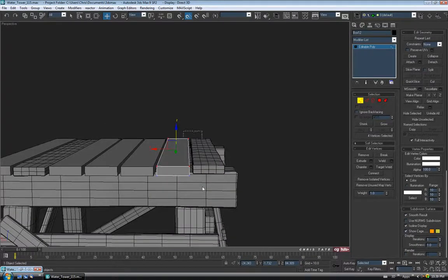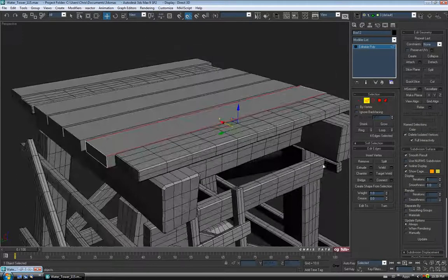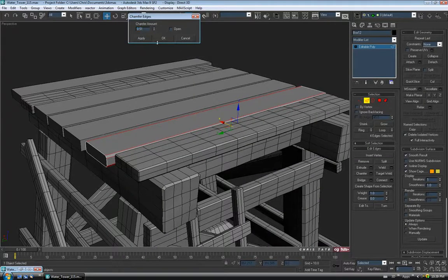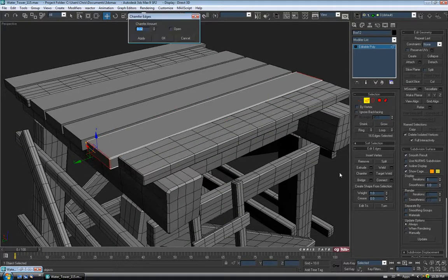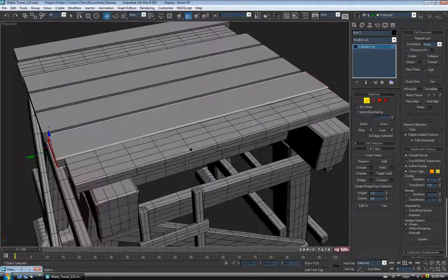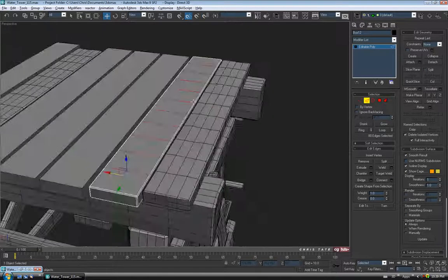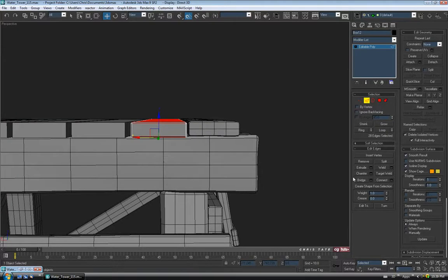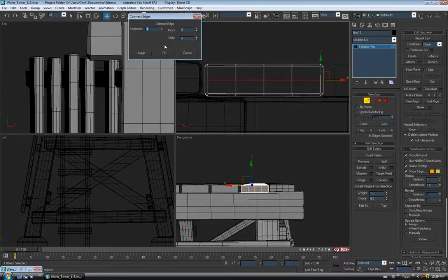So we'll leave the height pretty much as is, but we can play with the width and the length. So I might make this one a little bit wider by just pulling these side verts over just a bit. Alright, and then we'll chamfer it down. Alright, let's go down a bit. Alright, do this one a little tighter, maybe around 0.22 or so. Invert, chamfer again, and I'll just leave the end like that. Alright, so let's add our 10. Okay, and then we'll add our 3 this way. Back into the front view for a sec, and just drag through the side, and add our 1.